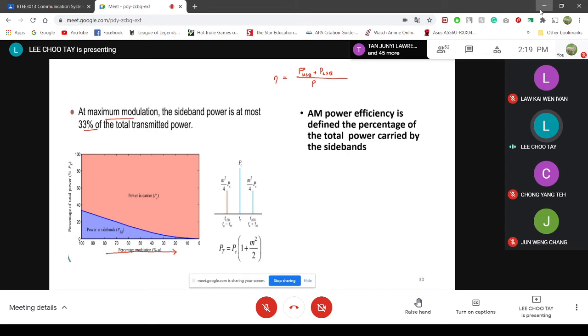If you look at the double sideband signal being generated, how well can you design your bandpass filter? Because what I was talking about just now is that I assume my filter is ideal, so I can filter the band that I want out perfectly, and transmit things as they are. This is when you can design a filter that performs ideally. But in practice, you know that an ideal filter does not exist, right?